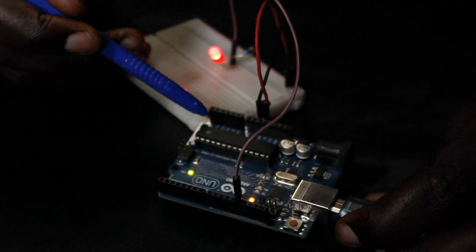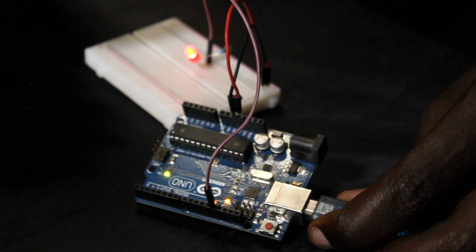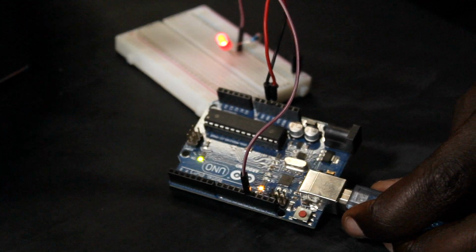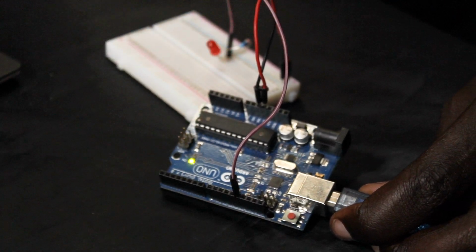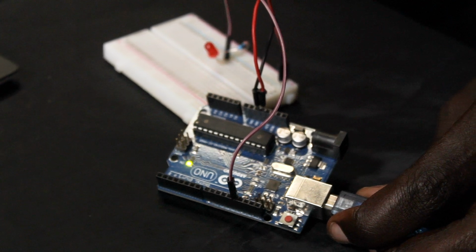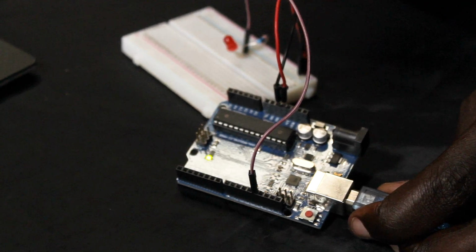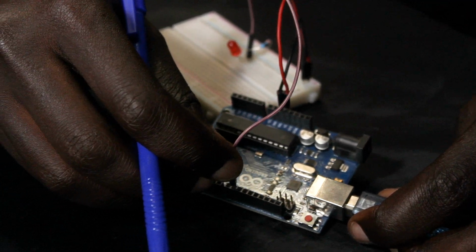What this means is that any one of those pins can be used to simulate an analog signal as an output. On this other side, you have analog pins that are inputs, so those read analog signals. But these specific ones that have the waves next to them can simulate and output virtual analog signals. All right? So in this case, we are going to use one of these pins, pin number 9.